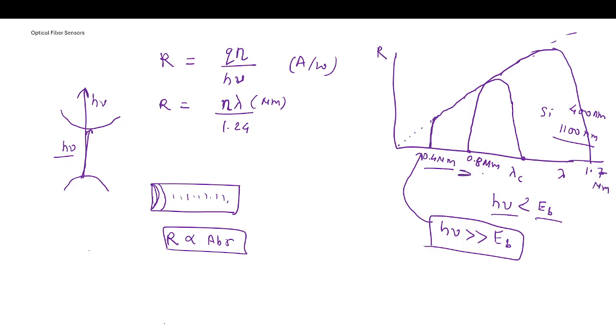But here also the same thing is happening. The power will decrease drastically because of the high absorption, it will not propagate through the path, so the current won't be produced and responsivity decreases drastically. So larger the absorption, smaller the penetration depth, and low responsivity.